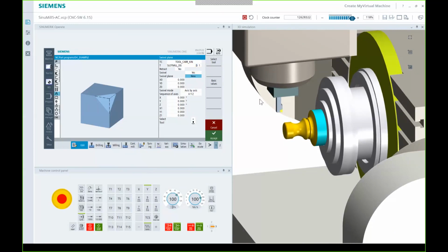What this cycle does is it takes my coordinate system and it moves it. These first fields, I like to say, are setting up a hinge, the place where you're going to perform this rotation. And we're rotating the tool. Even though it's a table machine, and I understand the part is the thing that's physically moving, we're really not moving the part. We always want to think about it in the sense that we're moving the tool, because, first off, it's the correct way to think about it.